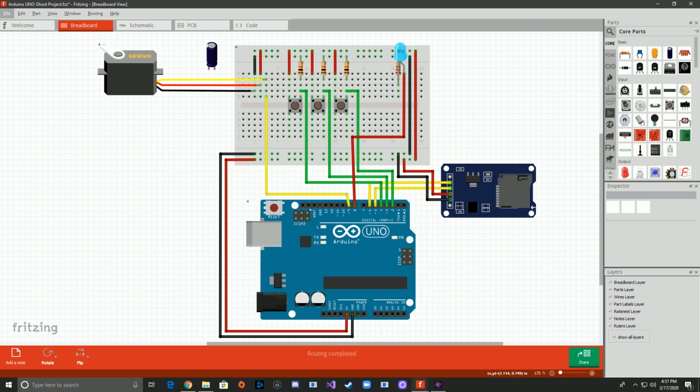Besides that, coming back up to the top left corner, you have it grounded out, and you also have power coming to it. Now I have a capacitor attached. Some people say that it's not needed. I like to put it there just in case. And do keep in mind, the capacitor will have a stripe on one side of it, either side, right? And it should be your negative side. So line that up with the other ground wires. You can see here, if we look at this black one here, it comes down vertically.